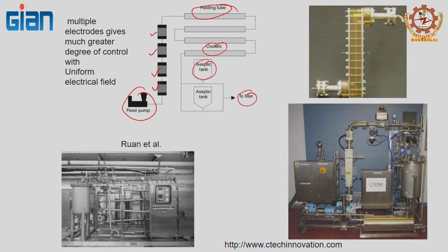Then you pass electric current through it, which warms up that material, say to 50 Celsius. At 50 Celsius, the electrical conductivity value may increase, maybe from 1.2 to 2. That allows more passage of electricity, so you can increase the temperature much more rapidly.